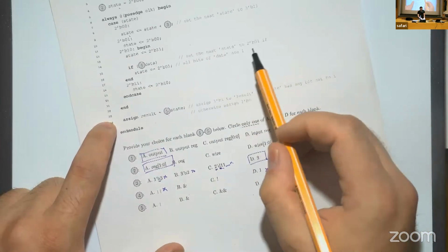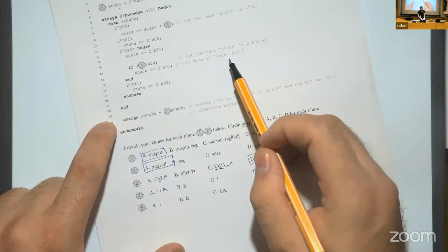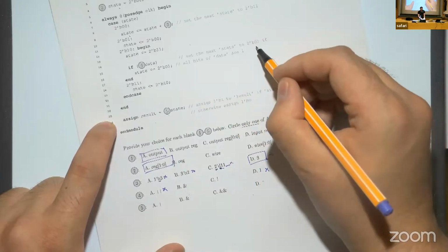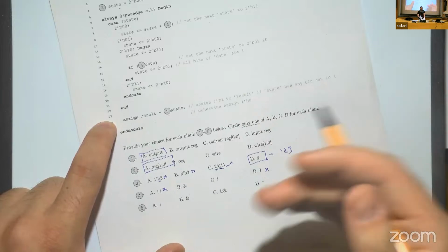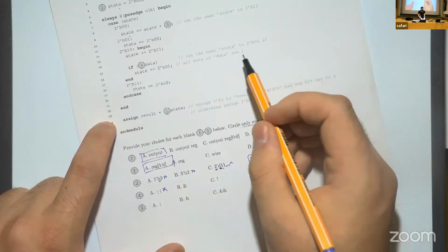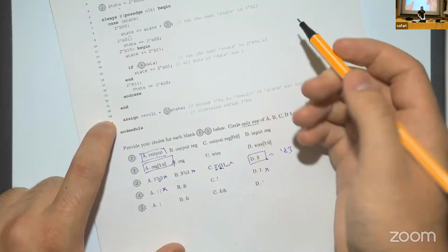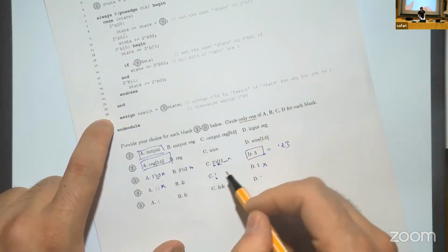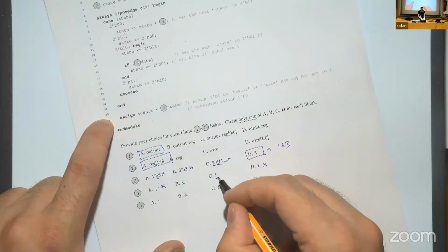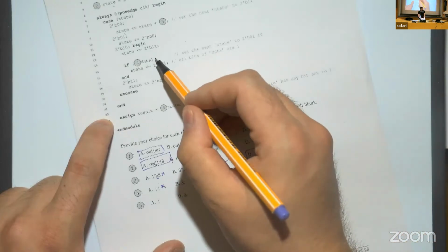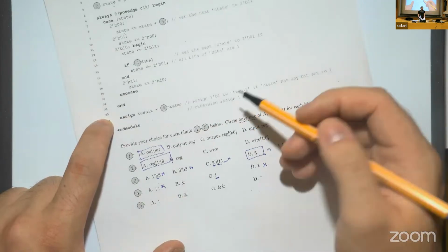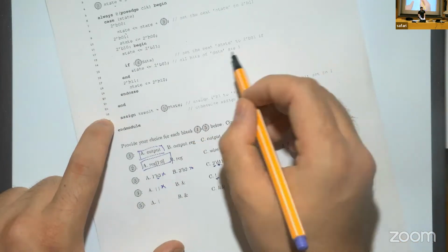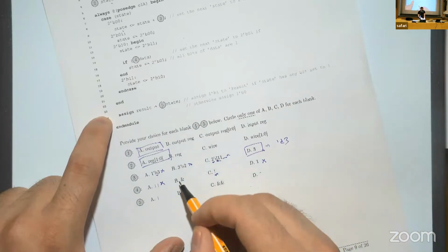We know that it says if all bits of data are 1. So which means that we have to perform AND reduction, and then we will understand whether all the bits are 1, right? If we use C, it's a logical negation. We have 8 bits of data. It will get the least significant bit, and that's why you won't satisfy this constraint. So the correct answer is B.